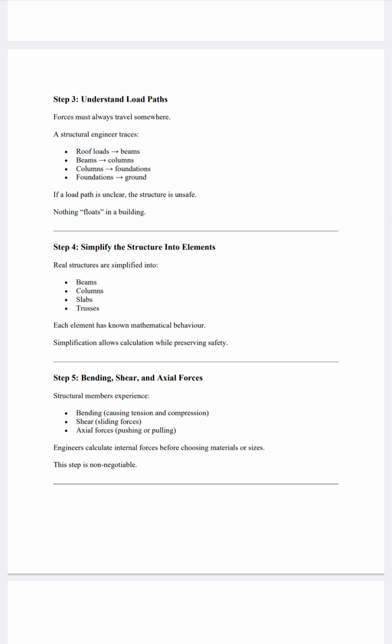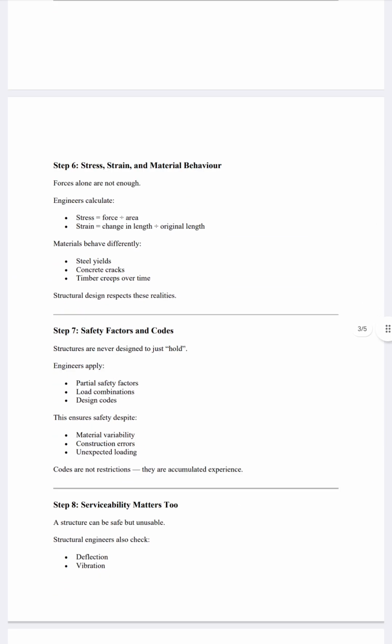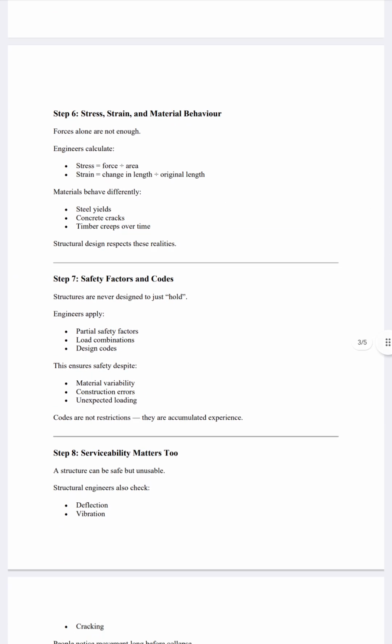Step 5, bending, shear and axial forces. Structural members experience bending, causing tension and compression; shear, sliding forces; and axial forces, which are pushing or pulling. Engineers calculate internal forces before choosing materials or sizes. This step is non-negotiable.